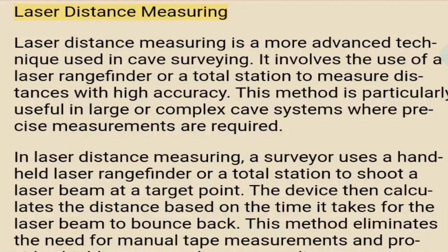Laser distance measuring. Laser distance measuring is a more advanced technique used in cave surveying. It involves the use of a laser rangefinder or a total station to measure distances with high accuracy. This method is particularly useful in large or complex cave systems where precise measurements are required.